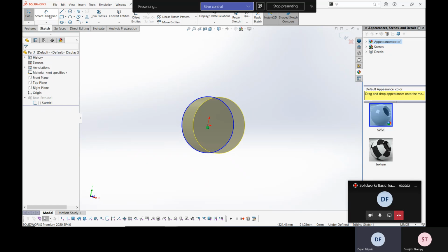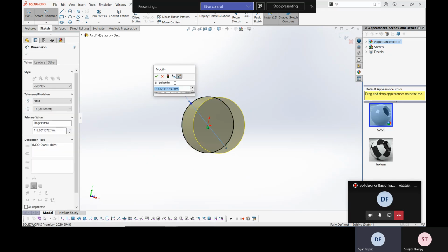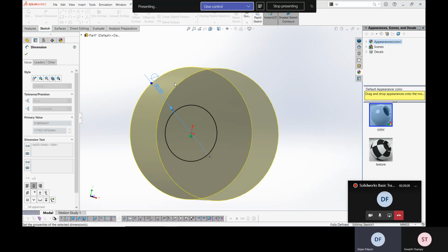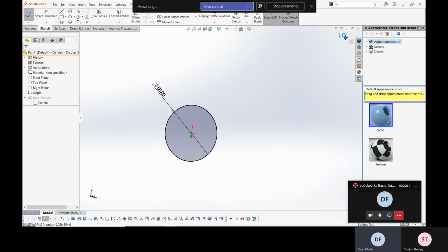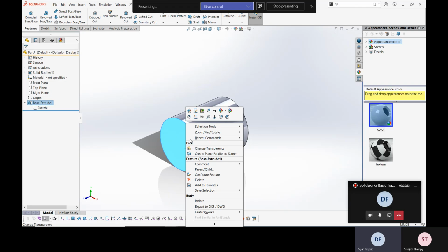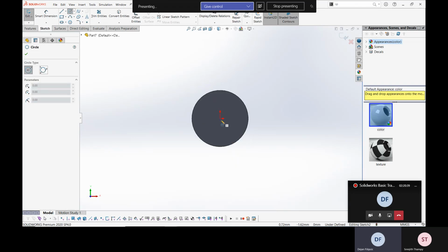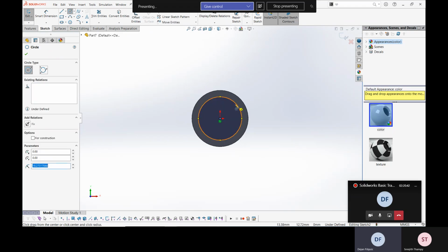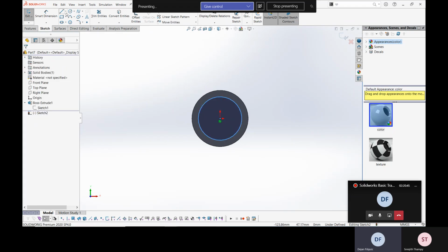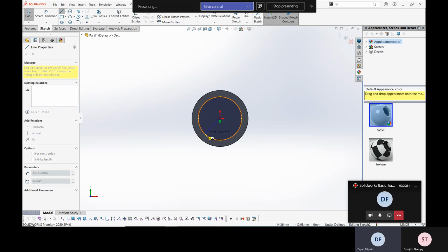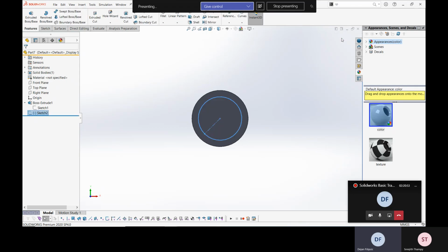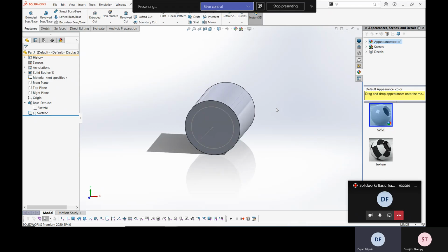For example, I've done injection molding when I started doing engineering. So what was a good way back then was that you had a number of plates, and then you had guides and this and that and bolts and whatever. You could create a couple of patterns. So two sketches with points, and then when you went across all of those plates, you can just simply click on that sketch and it will create the holes across all plates, if you didn't want to use the function that SolidWorks has to automatically do holes across a number of different members, right? But there's a number of different ways to achieve the same thing, and depending on the way you're working and what your preference is, you can pick and choose the one that works best for you.